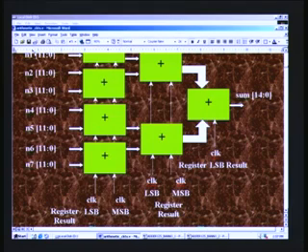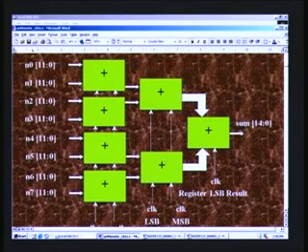will add N0 N1 LSB alone here, and register at the first register here when the first clock strikes, and similarly in parallel we will also be adding N2 N3 N4 N5 N6 N7, and with the arrival of the second clock pulse we will be adding the MSB together with the carry generated during the LSB phase. So out come 4 results here, and we repeat exactly the same thing here by 2 more adders in the second stage. This is the first stage, this is the second stage, this is the third stage, and once